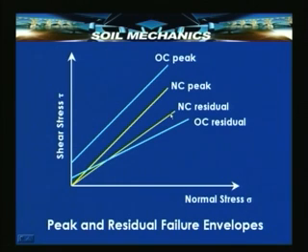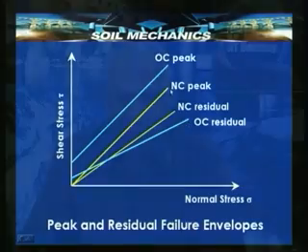Whereas, if we have an over consolidated clay, the peak will be much more than in the normally consolidated soil, and it will even show a small amount of cohesion intercept. And as I mentioned, the drop from peak to residual in the case of over consolidated soil is much more than in the case of normally consolidated soil, and therefore, the over consolidated residual strength envelope will invariably be below the normally consolidated residual strength envelope.